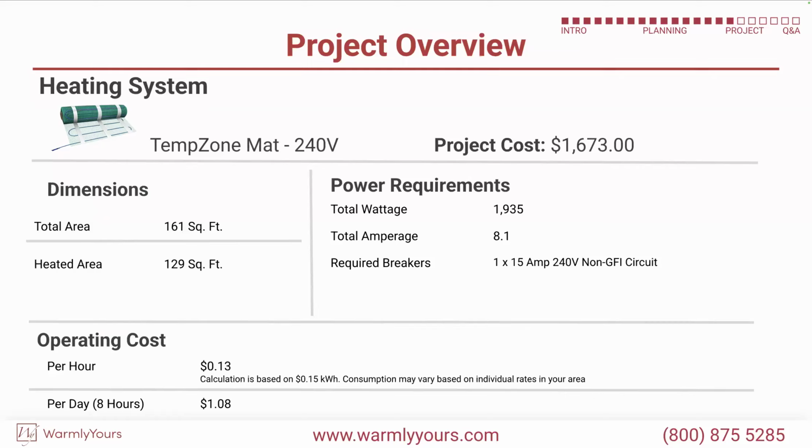Keep in mind that it's very, very important for some people. And I run into this case quite often where they only want to run one circuit up to a small bathroom on one side and another small bathroom on the other side. So they only want to run one circuit up, but now they're feeding this thermostat and feeding this thermostat. And now these two thermostats are on one circuit and this one kicks off, the other one sees that as a problem and shuts down. So you cannot have two GFCIs on the same circuit.